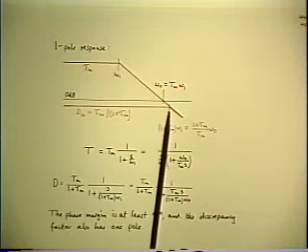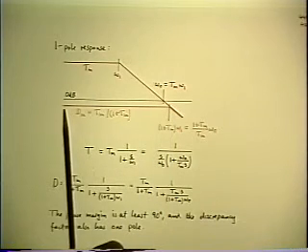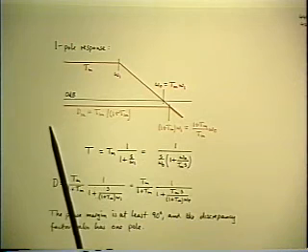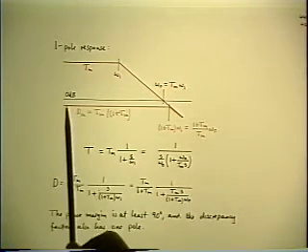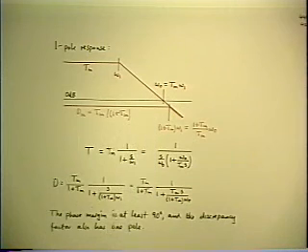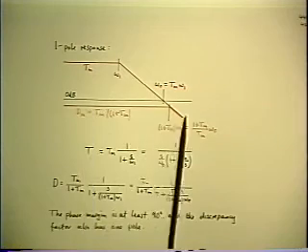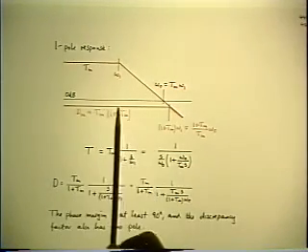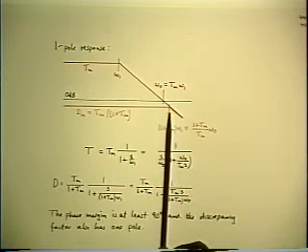And it has a single pole which is on the same asymptote as the original T. And the next step is you multiply the D by the G infinity to get the closed loop gain. Well, we don't need to go through that step anymore at the moment because it's the shape of D that is going to determine that result. And the objective is to get D as close to 1 as you can, which you do by making the loop gain large. However, you still have to account for the fact that it's going to go away eventually.